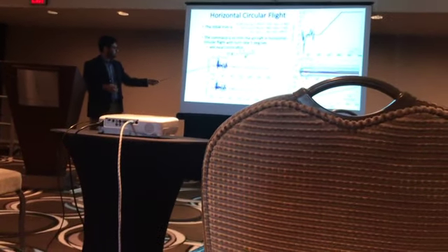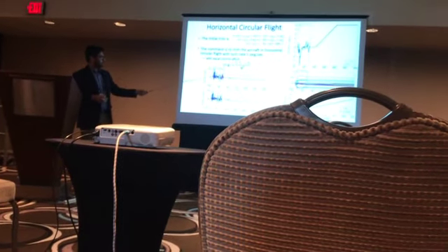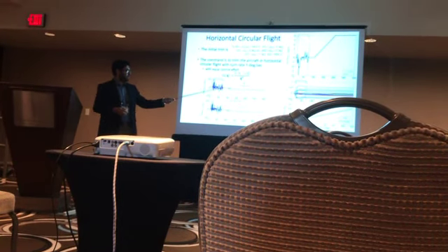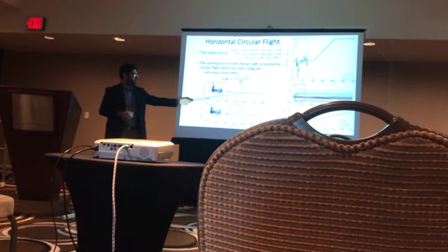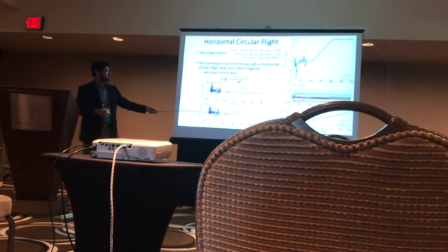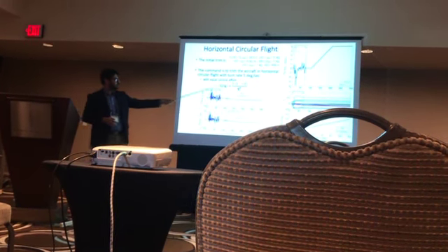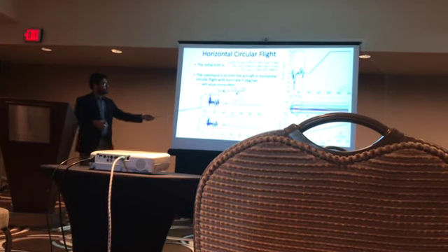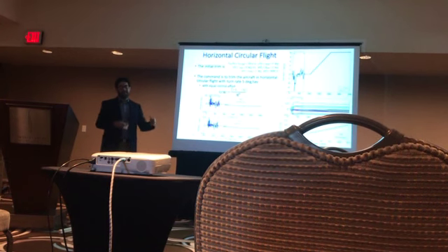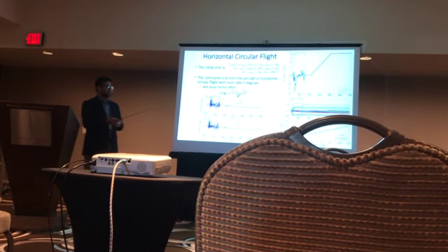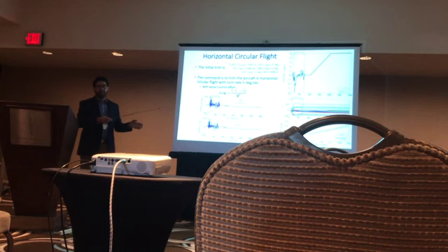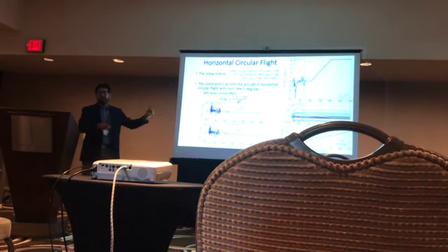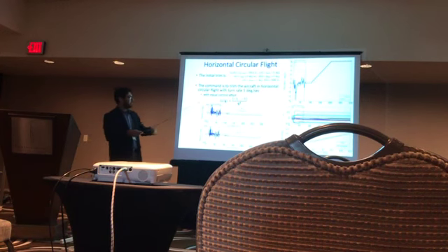So this shows the rudder and the aileron responses. So there's an initial transient, and then finally it converges to the value where it needs to converge. And both of these are always in the ratio 1:1. Now blue shows what we request, and since there is actually aerodynamics, there's going to be slightly different values that are applied to the actual aircraft. So reds show, no, I said it backwards. Red are the requested, and the blue are the actuals.